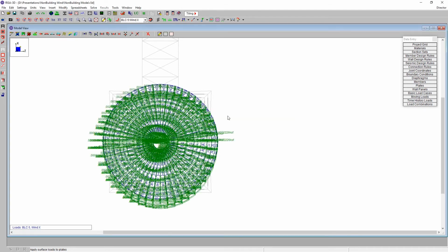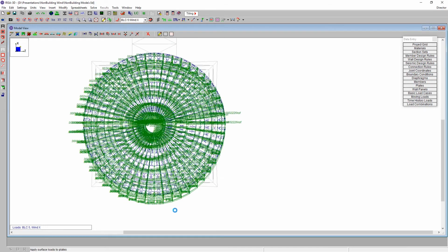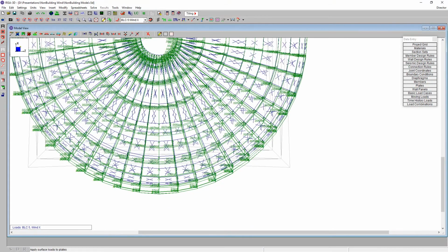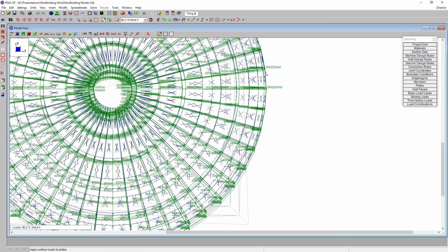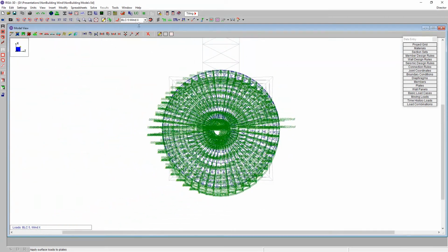And when I hit apply, what we'll see here is that this wind load is projected such that when the wind load is blowing straight on in the x direction, perpendicular to the tank, it's up at that full 10 psf, but that load actually tapers down to about 0 as the wind is tangentially blowing past it, since of course we wouldn't really have any wind due to friction or anything like that.